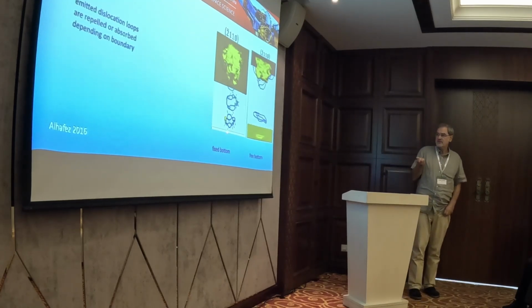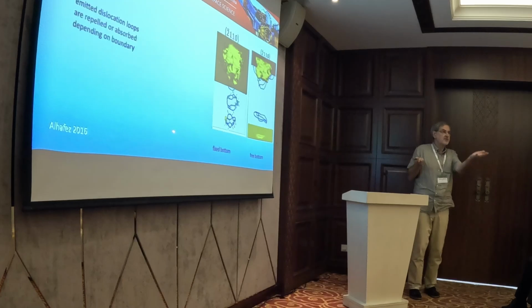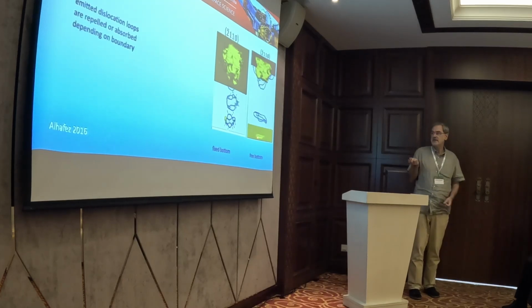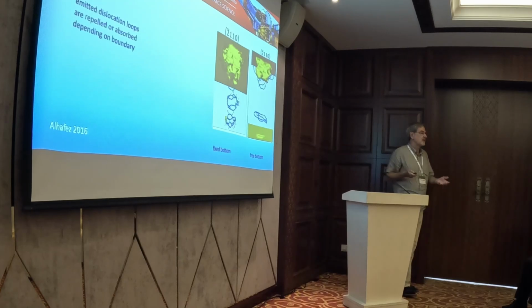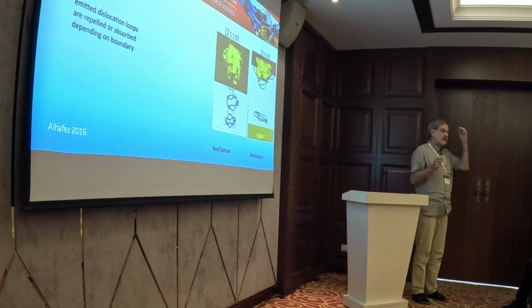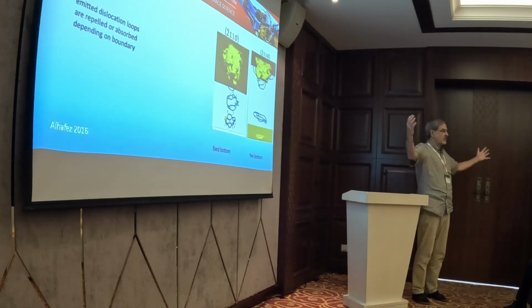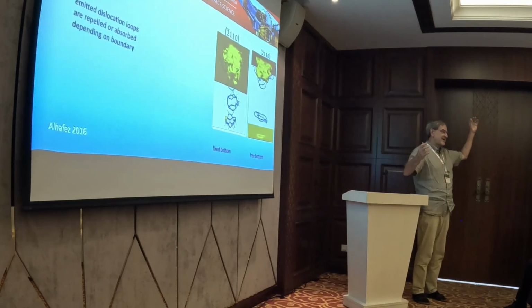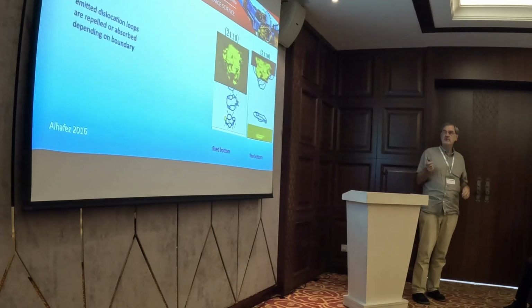And you have a fixed boundary surface at the bottom surface. What happens is the dislocations will be repelled from the bottom, so they stay inside the material. If you have a free bottom, they will just be absorbed. It's a boundary. This is just to make you aware that boundary conditions matter. Usually you do have to have some conditions at the boundary because you cannot afford 200 million atom simulations. You use boundaries, but this is a warning. Be careful. Think about what you do.